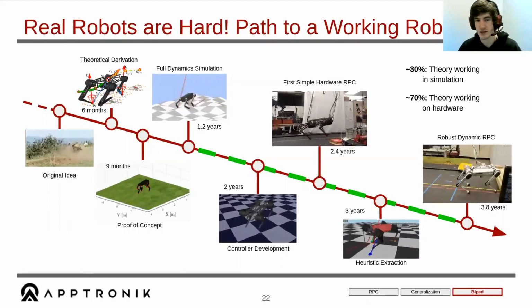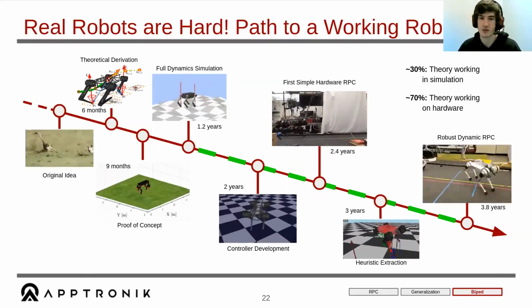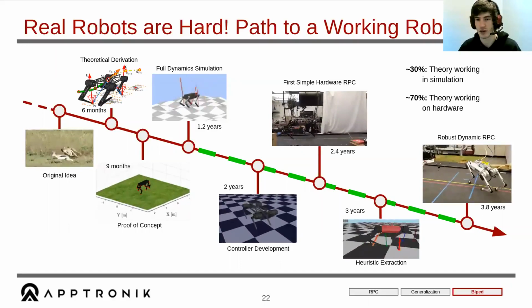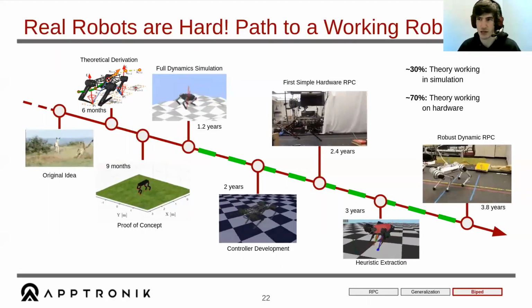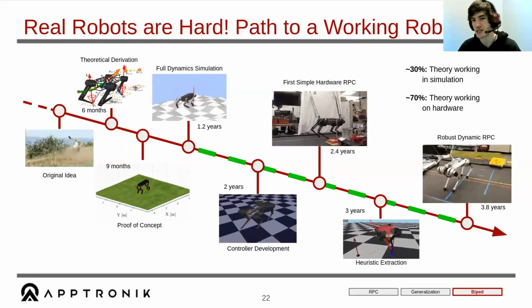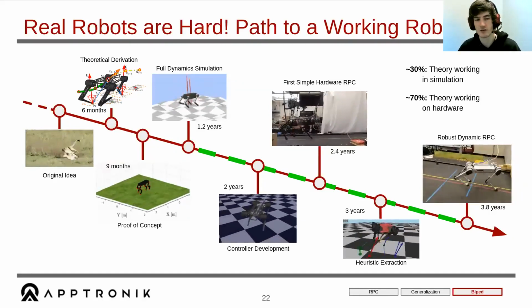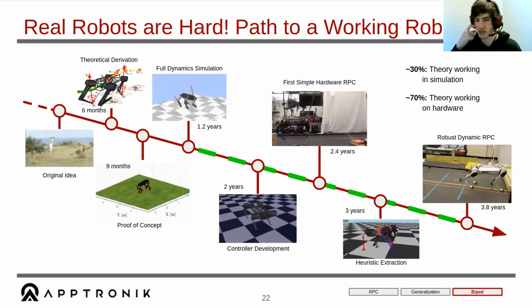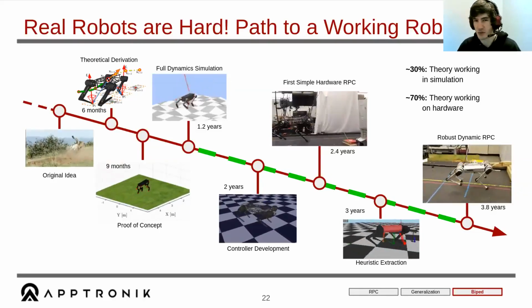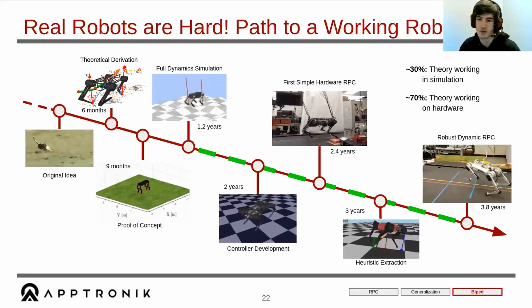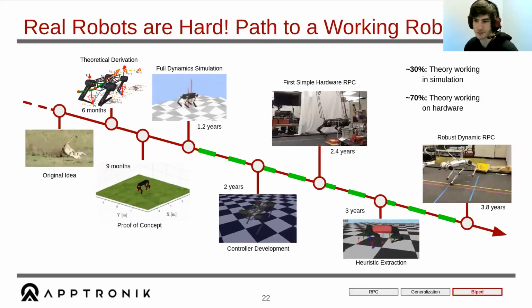Although I will say that instead of the 200 hertz that we get on the desktop or on Cheetah 3, we were running it around 60 to 80 hertz, which is still plenty of recomputation to actually stabilize the robot. Anything above 20 hertz I found works for the Mini Cheetah.